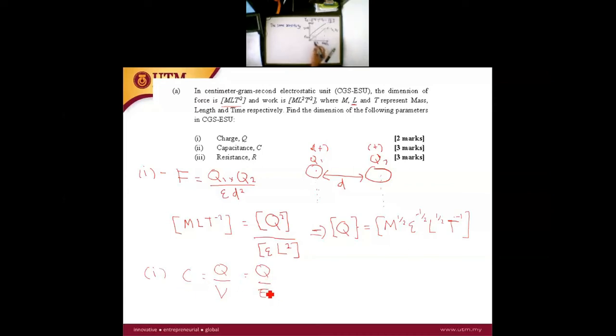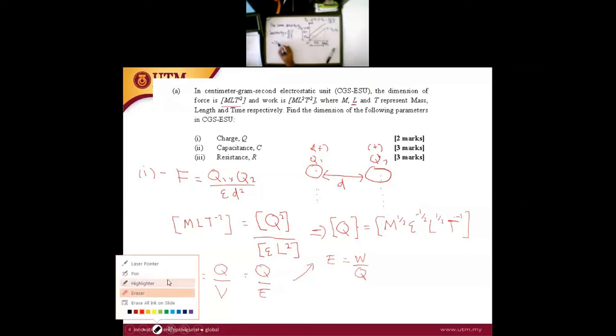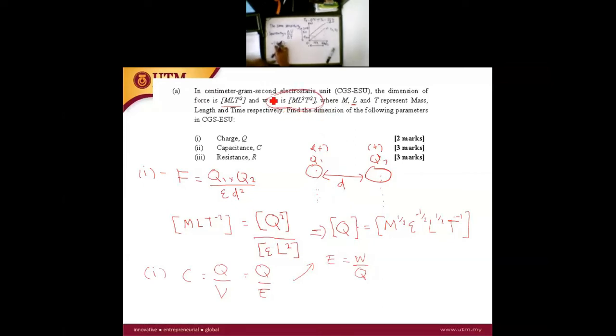So how can we calculate the sensitivity? Okay, we can take from the origin, origin meaning 0. So the sensitivity of the thermocouple is equal to delta V over delta T. So this is going to be our delta V over delta T, V2 minus V1 divided by T2 minus T1. But this is confusing, don't use this term. It's a different point.